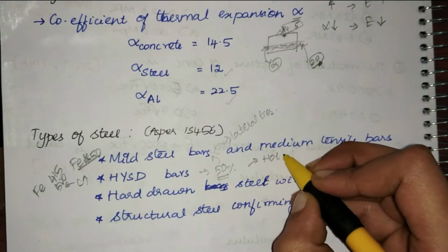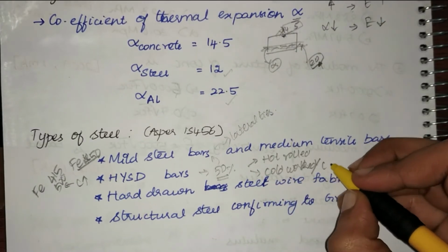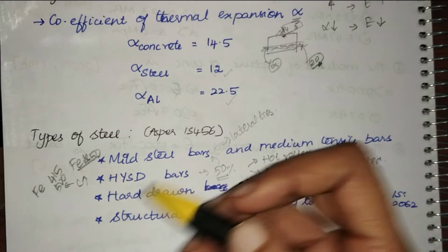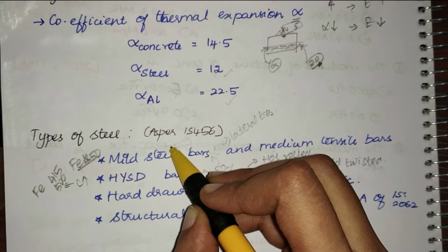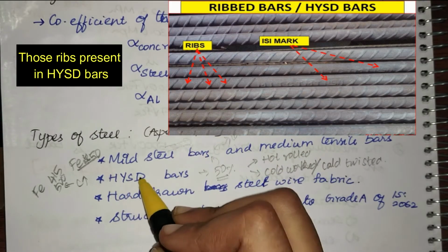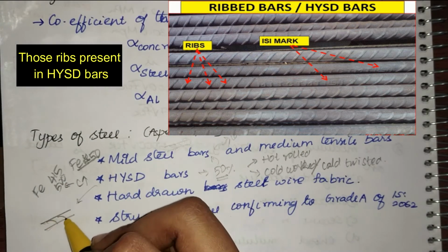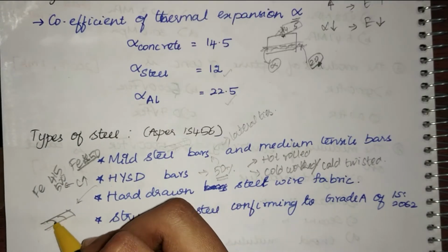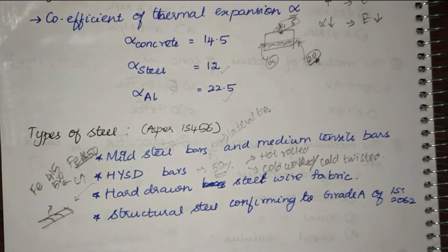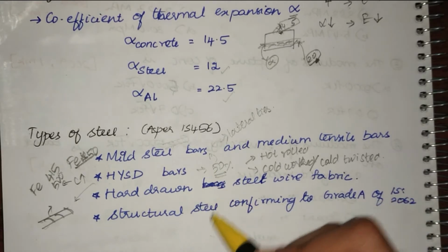These bars are of 2 types. First one is hot rolled bars, second one is cold worked, also called cold twisted. So these mild steel bars are plain bars. They don't have any markings or indentations in them. Whereas HYSD bars have twisting indentations. We would have seen these twistings. This will increase the bonding between the cement paste and the steel, and thereby increase the strength of the concrete.